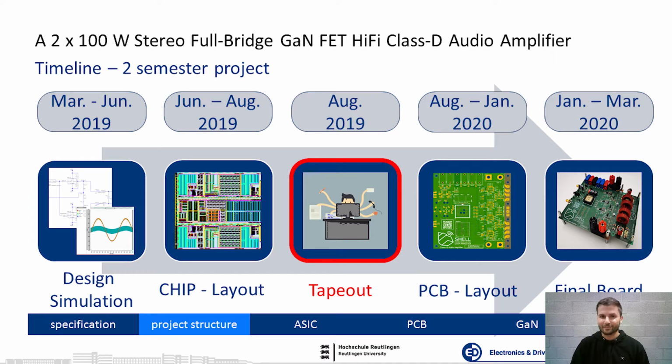In the second half, while the chip was fabricated, we designed and manufactured application boards. It took us several iterations to complete our final board. Several passive filter components were analyzed and compared. Layouts and the fast switching operation of the GaN drivers and GaN FETs were measured and optimized. In the end, everything went fine, and our system prototype was brought to life just before the end of the term.